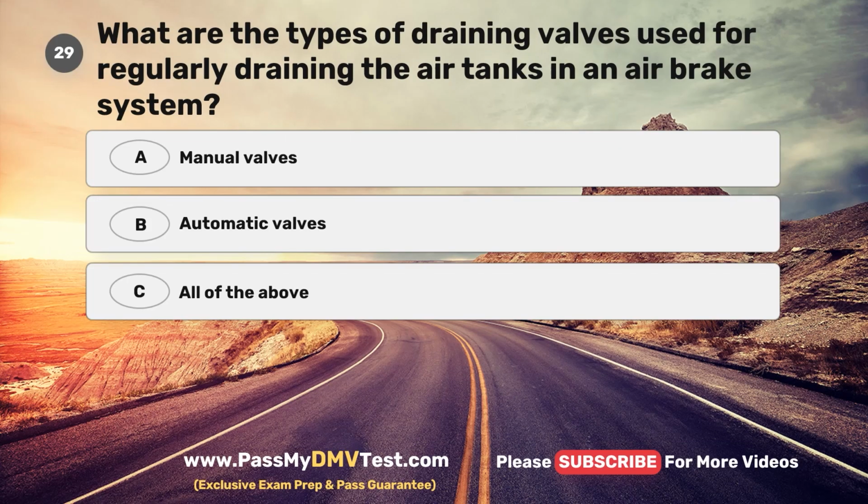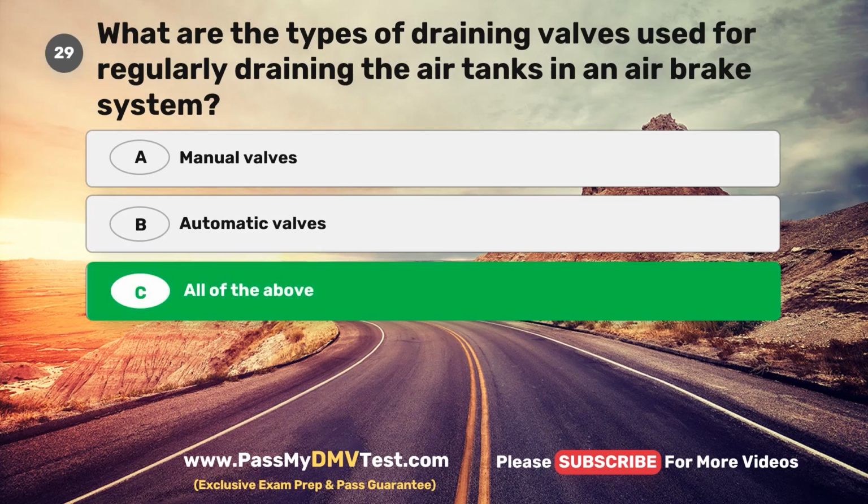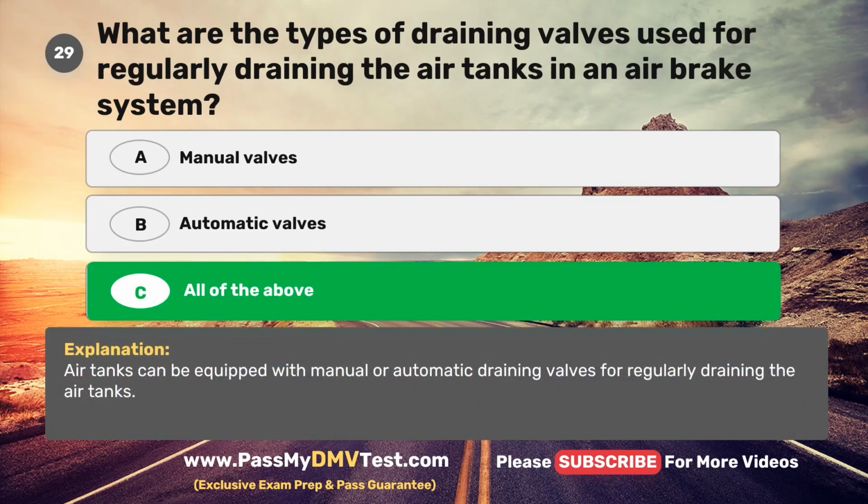Question 29. What are the types of draining valves used for regularly draining the air tanks in an air brake system? A. Manual valves. B. Automatic valves. C. All of the above. The correct answer is C. All of the above. Air tanks can be equipped with manual or automatic draining valves for regularly draining the air tanks.